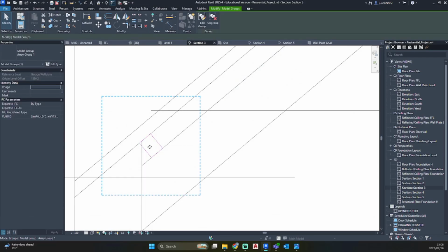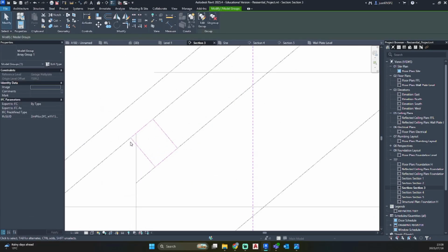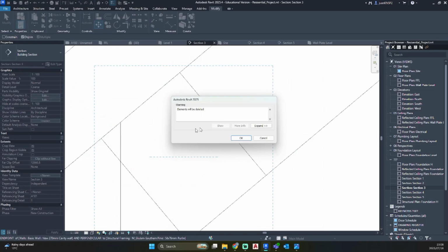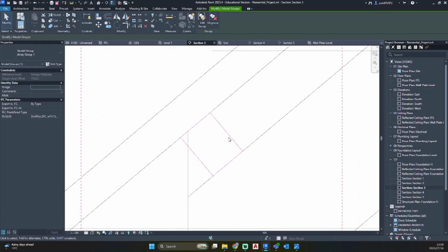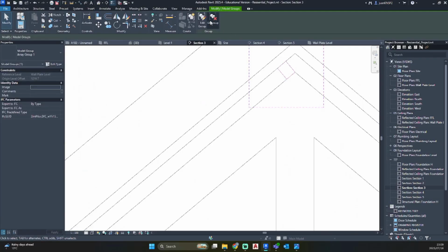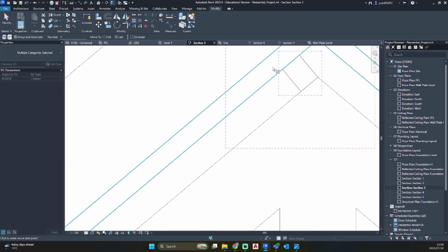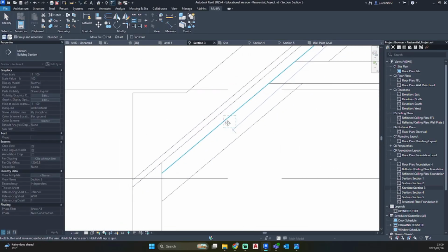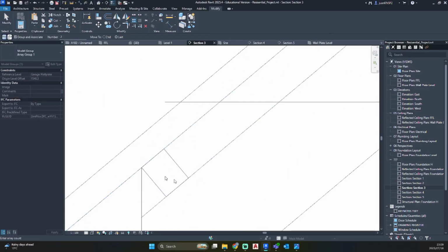But I want to move this up a bit because it's cutting into my wall. Since we can't move this element, I'm just going to select Ungroup, AR, select the left top side of my purlin and move that down to that area.